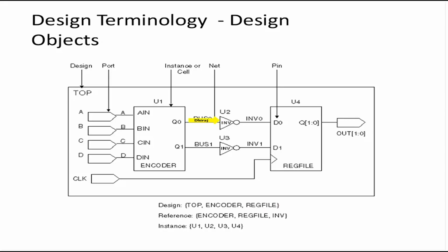Inverter here is a standard cell component. References are again encoder, reg file. So now inverter here, although inverter is not called a design, it can be a reference. We'll see the difference between reference and design. Usually when you talk about other tools apart from Design Compiler, you will not hear a term like reference. It's always design that is being used.